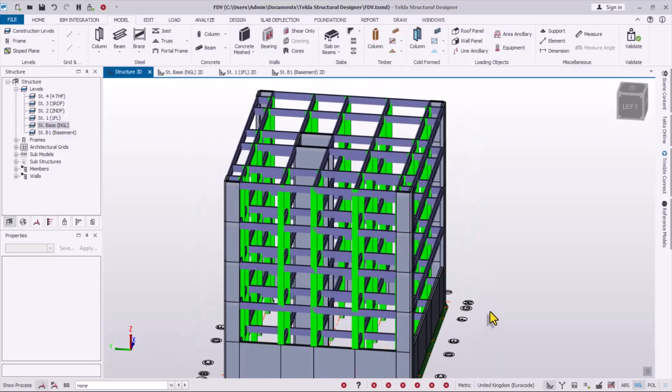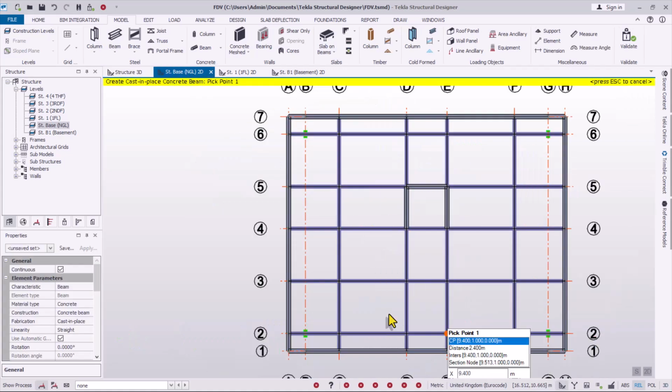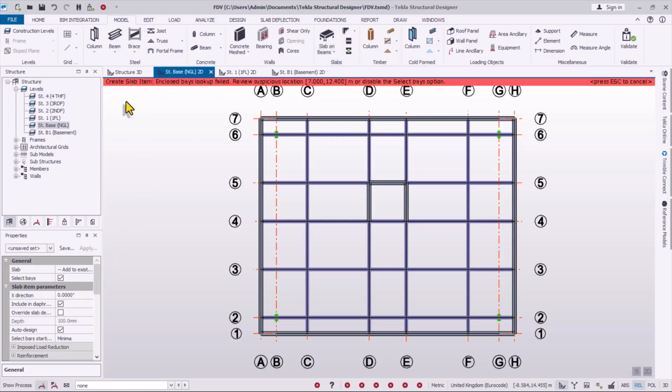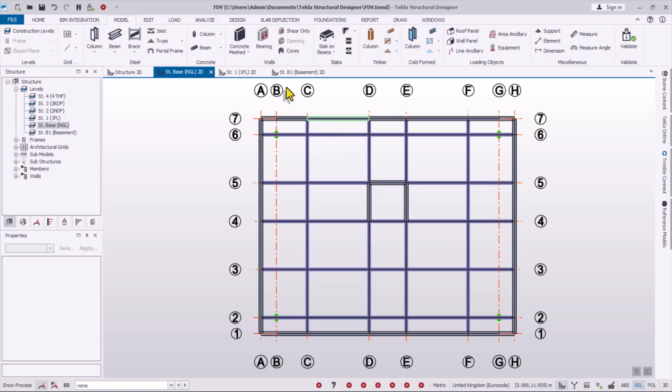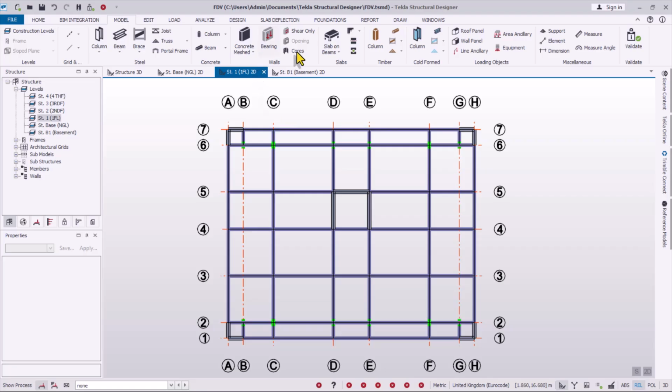All right, so now we want to apply the reinforced concrete slab. We go to the natural ground level. We need a slab right here, so just click on the slab on beam, the first option. Okay, so create slab item, close bar. Okay, escape that, go to the ST1. All right, here we go. This is ST1. We click on the slab provision.